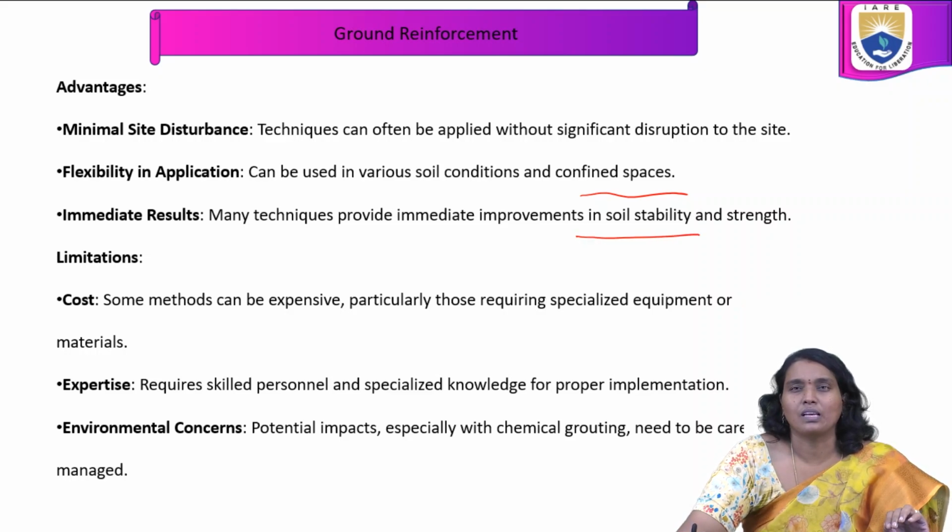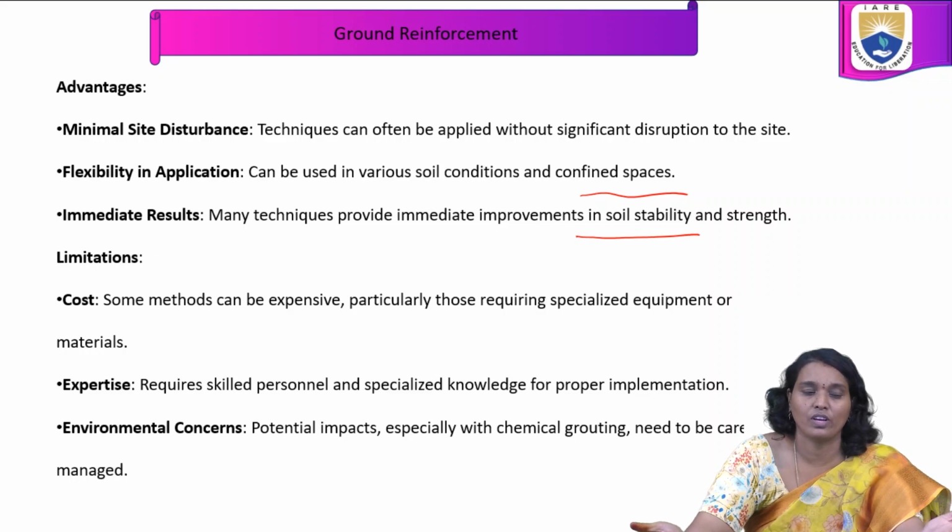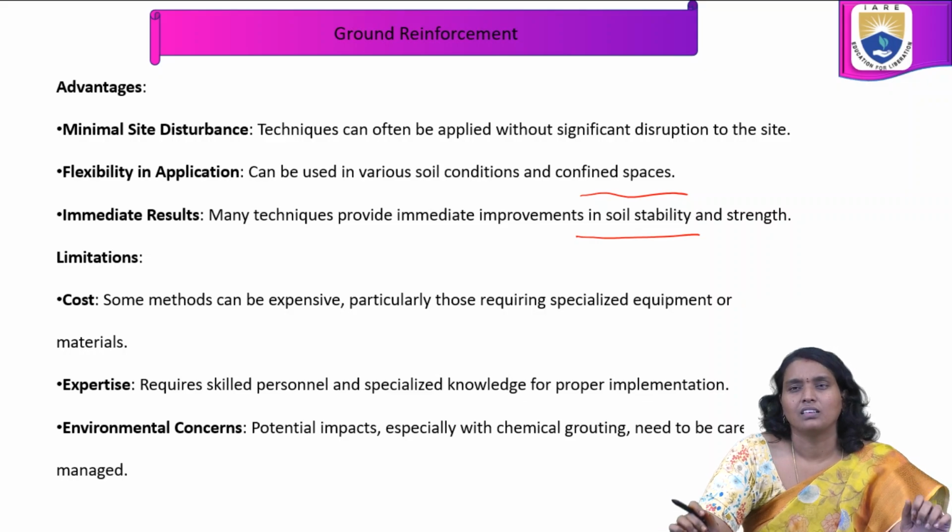There are also some limitations we are going to face in ground reinforcement: cost, expertise, and environmental concerns. Some of the techniques are expensive, particularly those requiring specialized equipment or materials, so it may affect the project cost. One more thing, it requires skilled persons and specialized knowledge for proper implementation, otherwise we are not getting 100% results for the reinforcement.